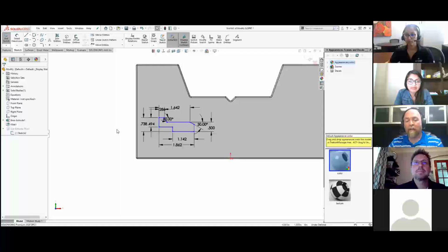The one caveat to this, and you'll see that I'm underdefined, is that if I try to use this modify sketch, it can't be attached to external geometry. So I can't snap it to another edge. I can't snap it to the origin. But if I can get rid of those, I can delete a coincident pretty easy, right? So I'm going to use modify sketch.